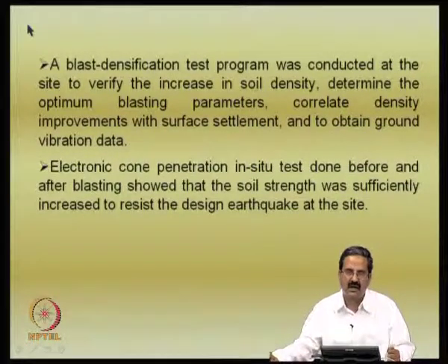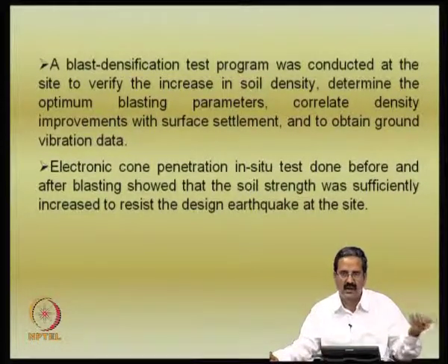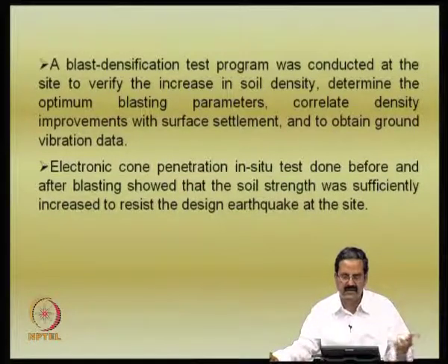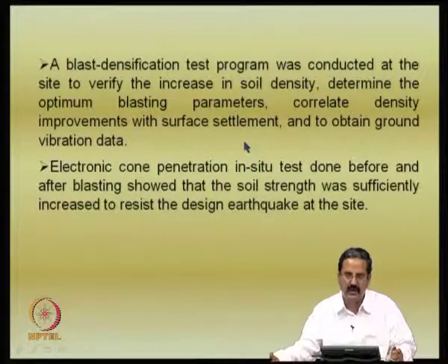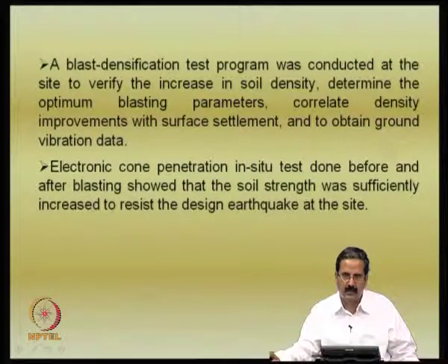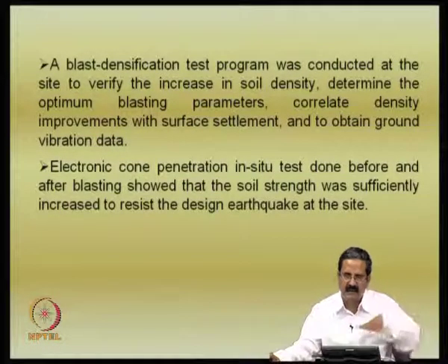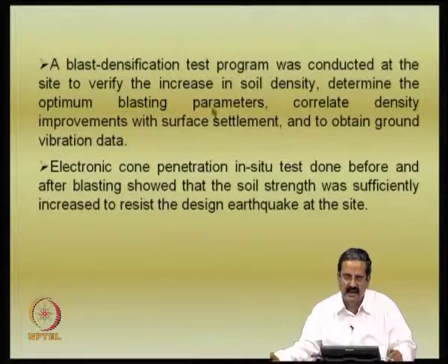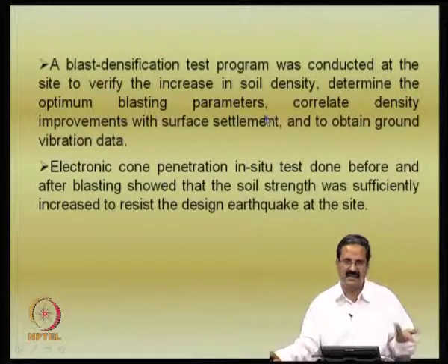In fact, particularly when you do blasting, the problem is the propagation of waves, and it should not cause damage to nearby buildings or facilities. Blasting may be useful to you, but it should not lead to problems for the neighbors. So, one should really measure the ground vibrations, like vibrations at the surface, vibrations with depth, vibrations in the lateral extent, and also correlate them with the surface settlements, density improvements, and blasting parameters, which are nothing but the charge and the spacing and all that.